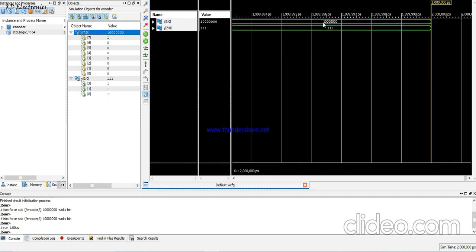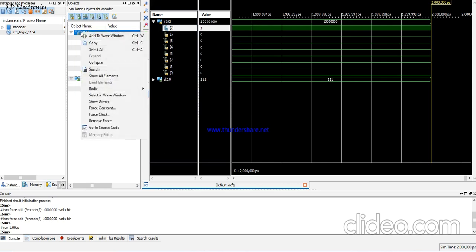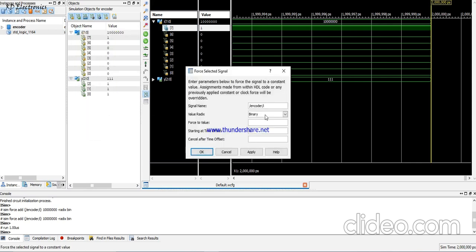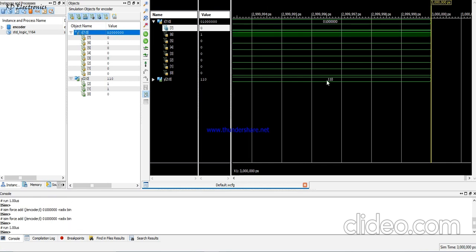Now see that when this is 1, that means this is I7, now this is the signal pin condition. Look here that the I7 pin equals 1 and all the remaining bits equal 0, therefore the output gets 1 1 1. Similarly, if we select 0 1 0 0 0 0 0 0, we select the 6th input, therefore the output becomes 1 1 0.